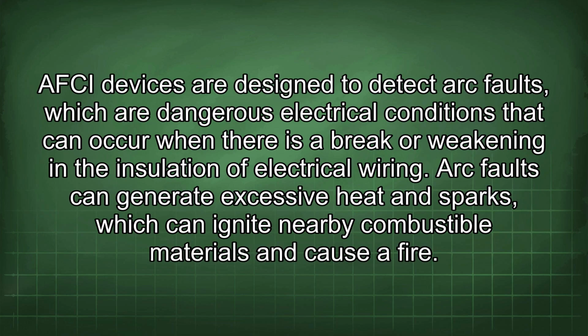AFCI devices are designed to detect arc faults, which are dangerous electrical conditions that can occur when there is a break or weakening in the insulation of electrical wiring. Arc faults can generate excessive heat and sparks, which can ignite nearby combustible materials and cause a fire.